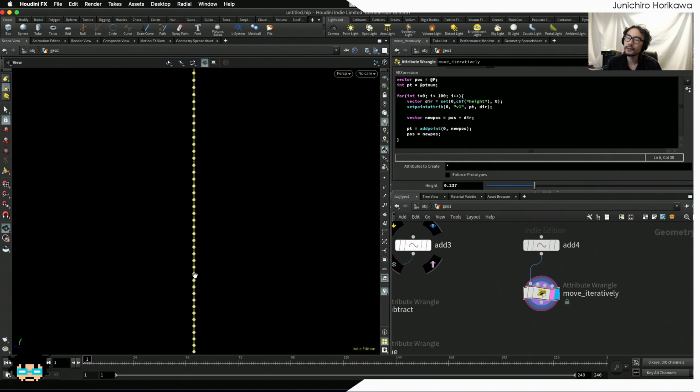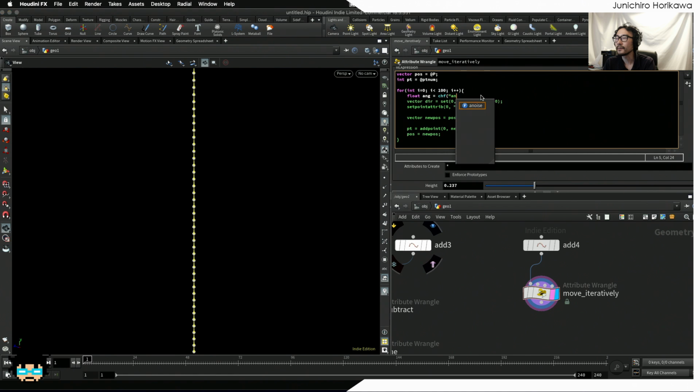Now, just going upward is a bit too boring, so let's try to make it a bit more interesting, like creating a spiral curve. To do that, we could use some simple trigonometry. First of all, we can create an angle value with a float. Let's create a parameter like ang between 0 and 1 and multiply by $pi, and as a result you'll get a value between 0 and pi, which means 0 to 180 degrees.